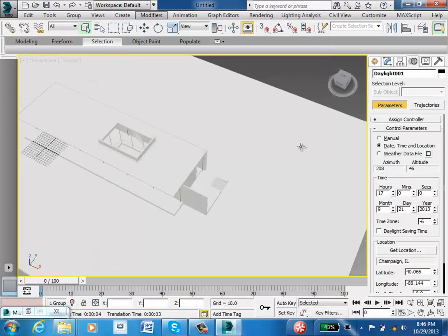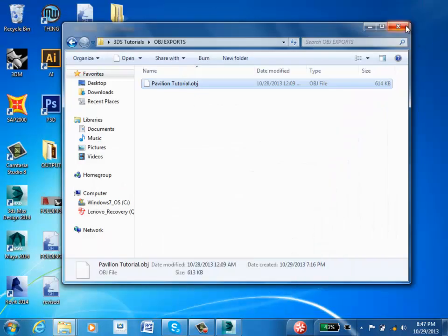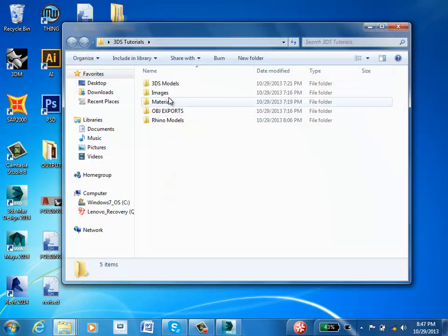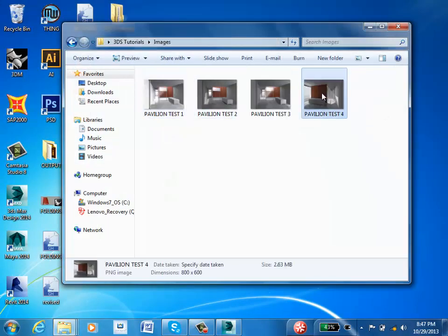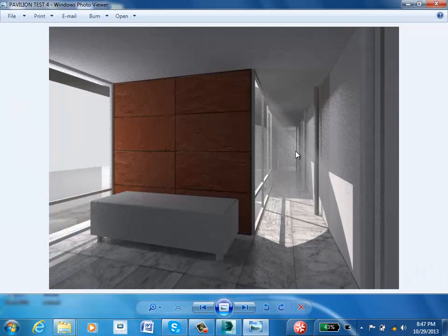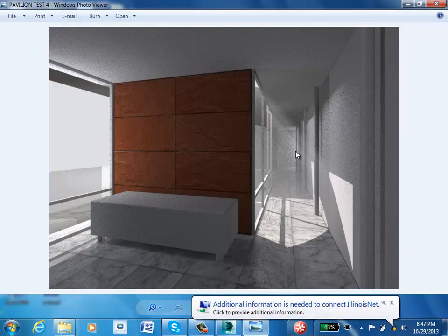So in summary, what we've done is we've learned how to import Rhino files in 3ds. We've covered basics of the interface, how to create and modify objects, and we've inserted a daylight system and covered render settings. On Thursday, we're going to delete that all-in-one lighting system. We're going to separate it into parts and control each light, as well as apply materials to an interior rendering. And what we're going to get as an output, just so you believe that it's possible to do, is a series of renderings, right, which start to have very interesting spatial qualities.